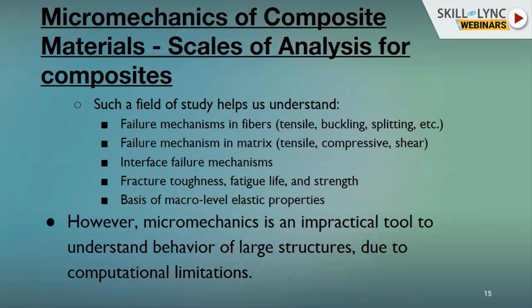So micromechanics will help you in understanding the failure mechanisms in fibers. Basically, when the fibers are subjected to tensile loads, buckling and splitting, etc. are various failure mechanisms that can happen in fibers. Whereas in matrix, again based on the load subjected, the matrix failure mechanism will be different from fiber failure mechanisms.